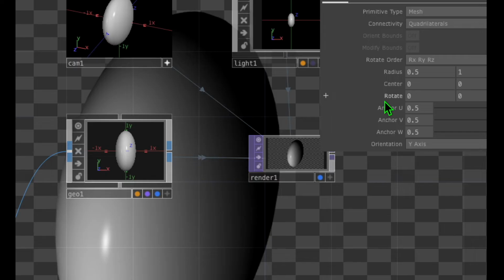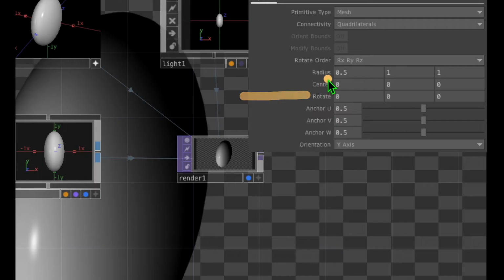And another really cool thing you can do in TouchDesigner is, instead of using the keyboard to input a new value, you can click and hold on a parameter and then move the mouse or the trackpad up or down to increment. So what we're going to do now is use a different method to modify a parameter that's super useful. Let's focus on the rotate parameter right now, and on the Y value of the rotate parameter. We're going to click and hold on the Y value of the rotate parameter, and then you'll see a little list of numbers pop up. These are the increments that you can use to change this parameter. So with the mouse held down, keep that mouse button held down.